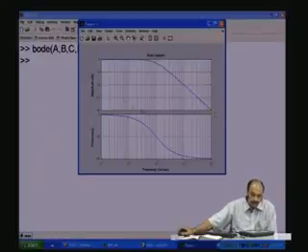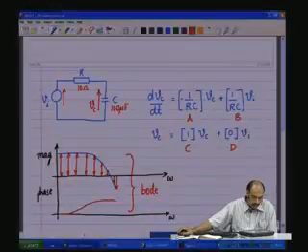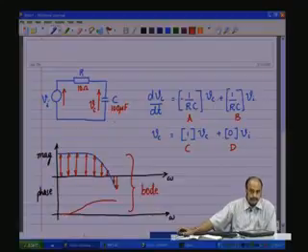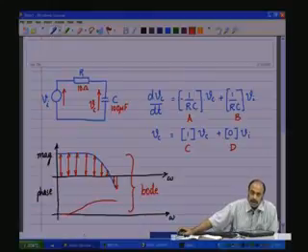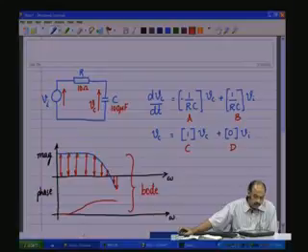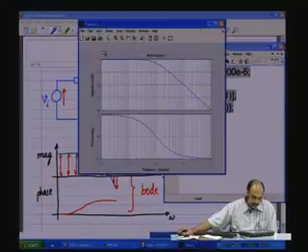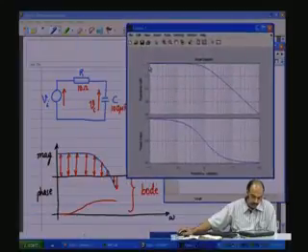In fact, it is also evident when you go back to the circuit, have a look at the circuit, you see here this is a capacitance and we are talking of output across the capacitance. So, what is interesting is capacitance blocks DC. So, it has a very high impedance to DC. It is like an open circuit for DC. So, this is the DC portion.